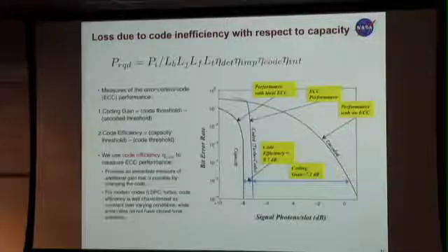With the advent of iteratively decodable codes like LDPC codes, concatenated convolutional codes, and turbo codes, you can get pretty close to this. So it actually makes a lot more sense. These are small numbers now, deviation from capacity, and they're like numbers that should be tabulated in a loss equation, a loss in the link budget. So aim for capacity and say how far away from capacity your code can get.